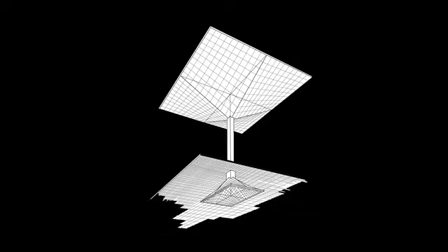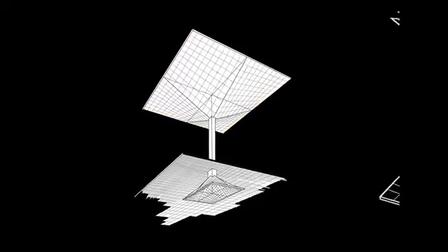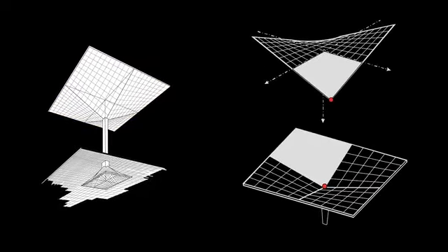The umbrella also has as a foundation another umbrella form. So this umbrella foundation essentially cups the earth in this high seismic region of Mexico City. We could look at the umbrella and separate it into 4 parts, and each of those 4 parts represents essentially a Hypar formed that are joined in those valleys. So the sketches you see on your screen, you see the straight line generators that create this warp surface, the doubly curved hyperbolic paraboloid form.